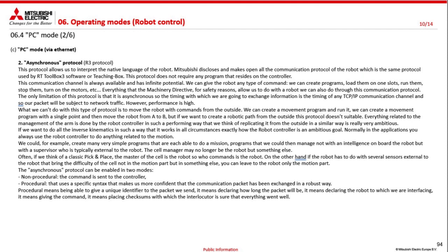Let's see what the second protocol is, called the asynchronous protocol or R3 protocol. This protocol allows us to interpret the native language of the Mitsubishi robot. Mitsubishi makes open the entire communication protocol of the robot, which is the same protocol used by the RT Toolbox 3 software or by the teaching box.